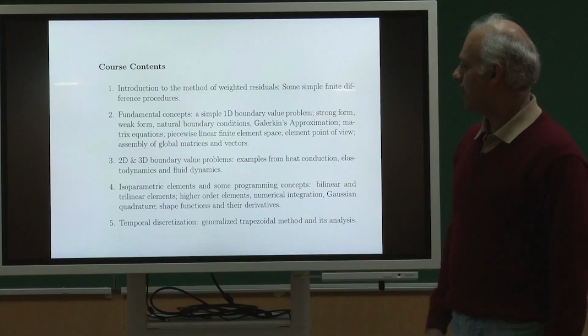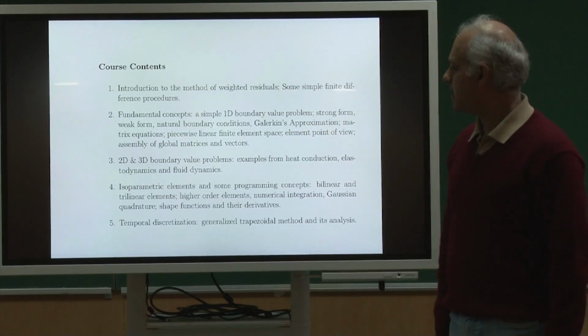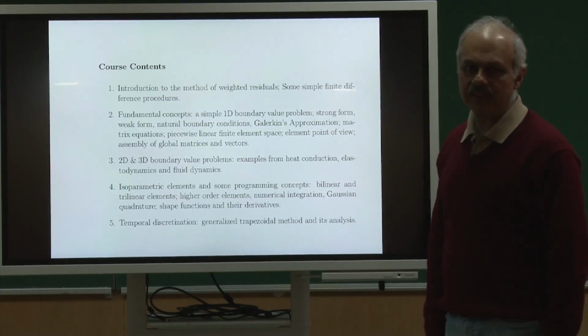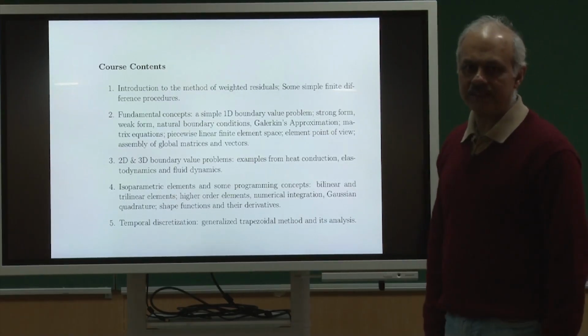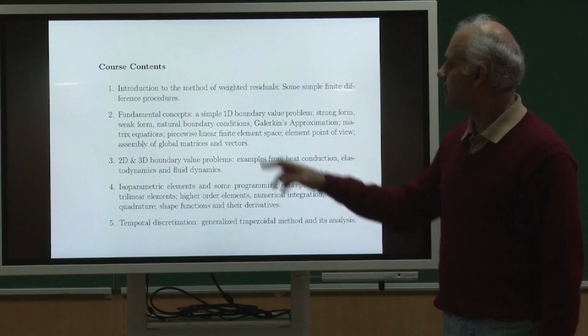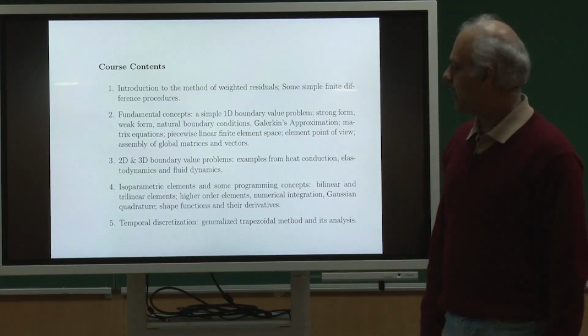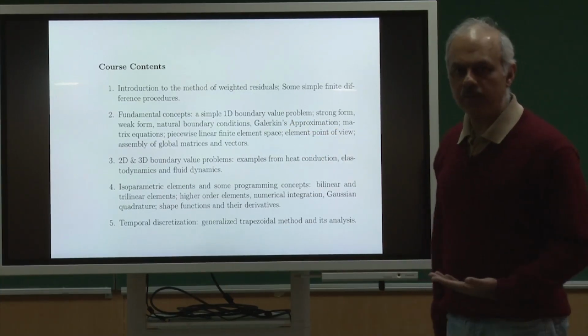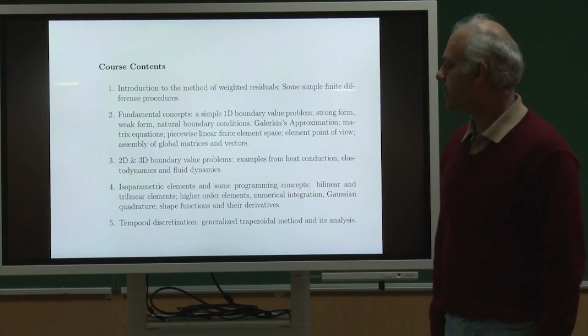And we will see that, as in other numerical methods, most of the time is actually consumed by the solution of a linear equation system. So, the beauty is we start with a simple ordinary differential equation, and by using the Galerkin's approximation, we will reduce the problem to something like Ax equal to b, just a simple system of algebraic linear equations.